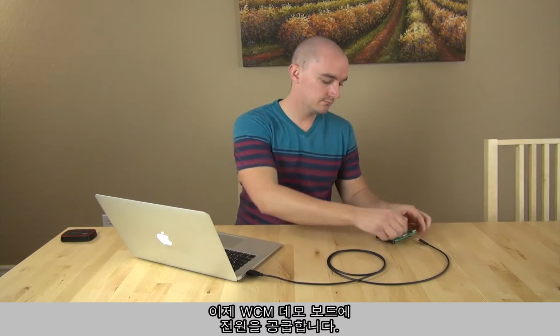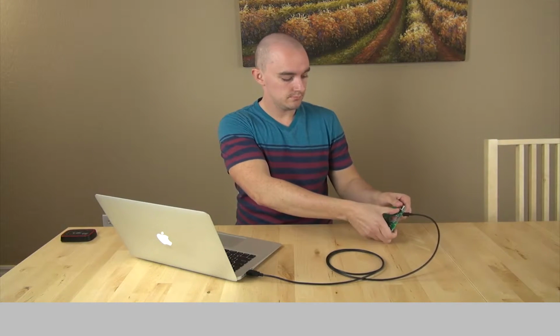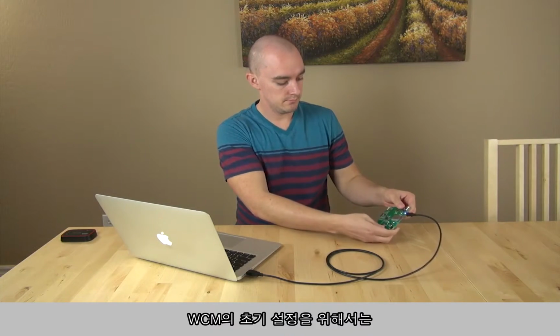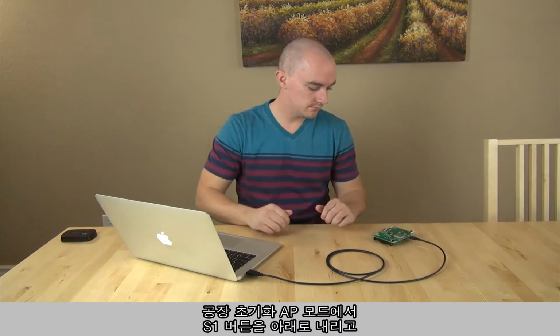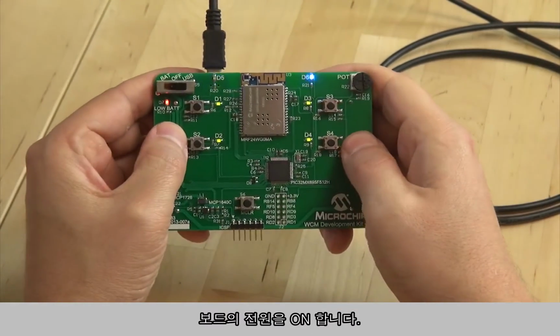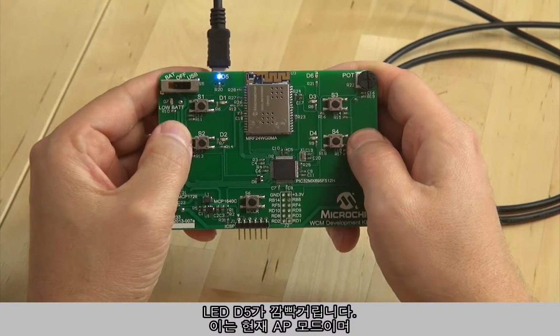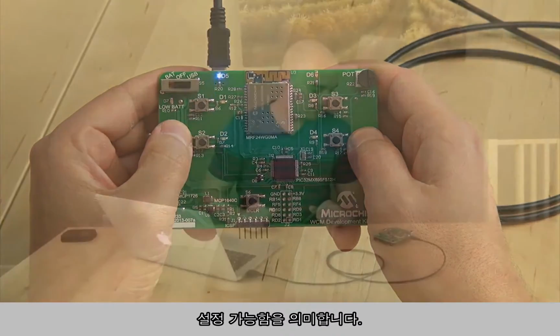The next step is to provide power to the WCM demo board. This can be done with batteries or a USB cable. For initial setup of the WCM, or to put it in factory AP mode, hold the S1 button down while turning on the power to the board. LED D5 will blink, indicating that it is in AP mode and can now be configured.